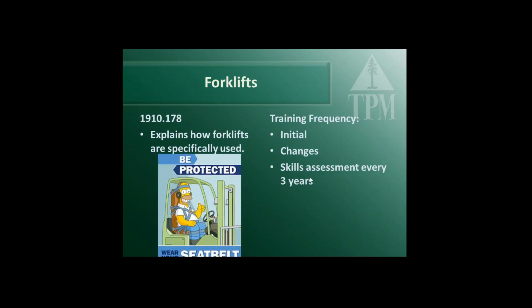Forklifts, basically initial and changes, and to keep your people certified from your company certification, every 3 years there needs to be a skills assessment. So you need to do the initial type of training, like a classroom training, and then every 3 years a skills assessment. That's the checklist, and that has to be done by your company. Some competent person you have there, someone that has some knowledge of it, running them well. Usually your most senior person is the best person to do it, because it's all layers of protection, right? So you want to look at the different skills that you do, lifting it up, backing up, the use of everything, the walk around, the inspections. So you go through that checklist every 3 years, and then document that, put that in their file so you can keep all the documentation of all your forklift drivers.